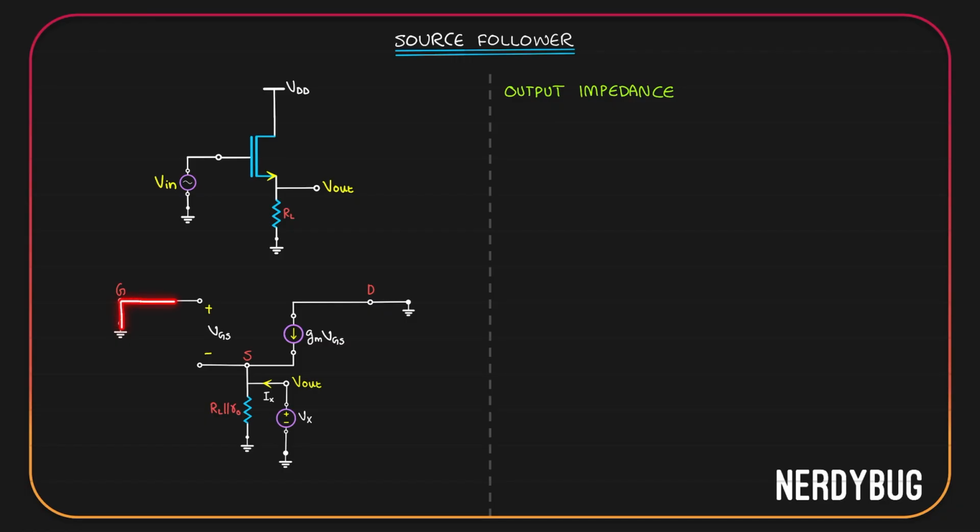As we go on, we see VGS from positive to negative. Further, as we go on, we have the potential across RL parallel to R0 and then we go back to the ground. Now, potential across RL parallel to R0 is basically just Vx with positive here and negative here. So according to the law, VGS plus Vx should be equal to 0, or VGS should be equal to negative of Vx. Now, let us apply Kirchhoff's current law at the source.